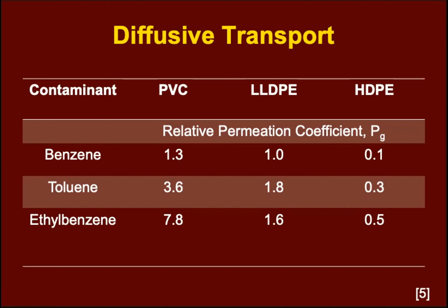But at the same time, for new and emerging contaminants, for contaminants that were not of great interest before, or for new liners that keep getting manufactured over time, these diffusion coefficients are unknown. Thus, in that case, diffusion tests need to be set up to try and estimate these coefficients for these contaminants through different materials and liners.